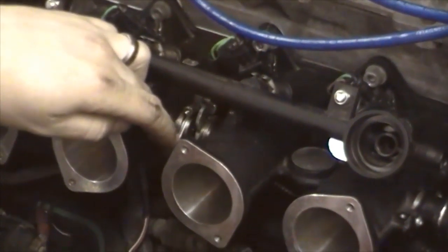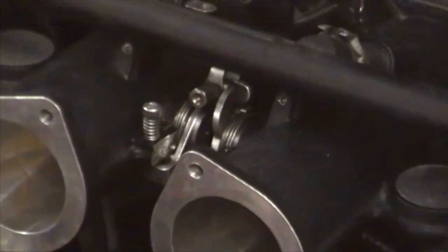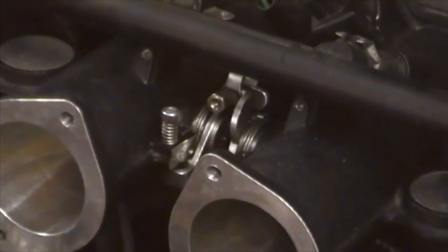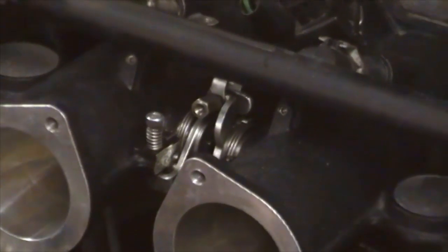If that is the case, just very slightly open it and you'll see it move off its base stop, and only do it a fraction of a millimetre, just so there's a small amount of air going in. If it's fully closed, like I say, it won't start. If you go too much, it's not a problem because we can always adjust the values, and we'll set that up a little bit later on.